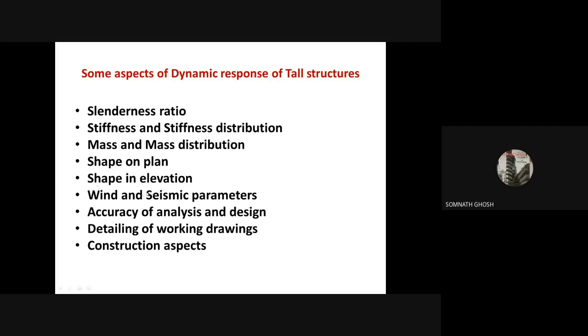That means when you are calculating wind forces, there are several parameters of that particular site regarding wind. Those things you have to consider carefully. Seismic is very, very important. If required, you have to go for microzonation, and then select the seismic parameters.